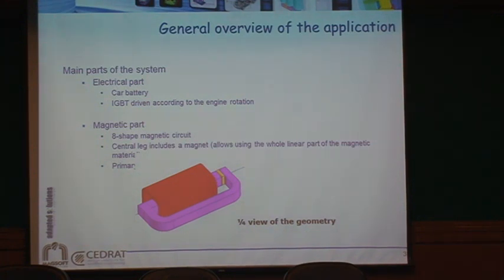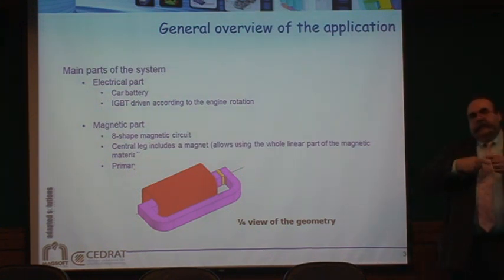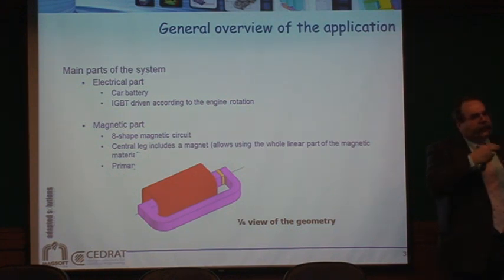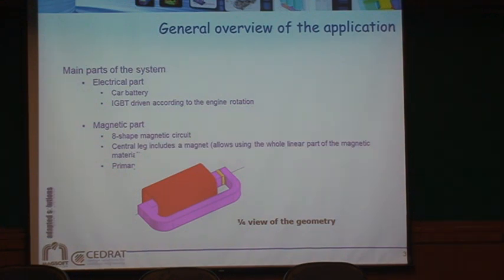I forgot the name. It used to be just little two pieces of platinum that when the rotor, the motor would turn, it would open them. That's how it used to open the circuit. I don't remember the name of it. But anyway, now it's actually done through a semiconductor. So it's actually better controlled, because before it was always associated only to the motor rotation, and it was difficult to change the angle of starting. So now, depending on the temperature of the machine, you can fire the IGBT earlier if it's cold, and later if it's warm, whatever.